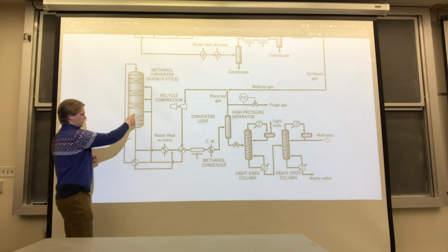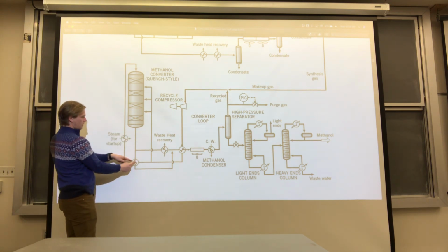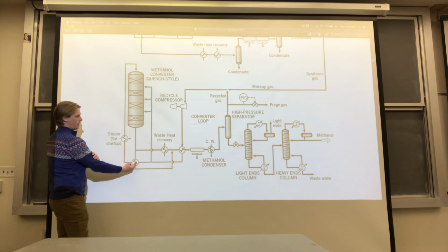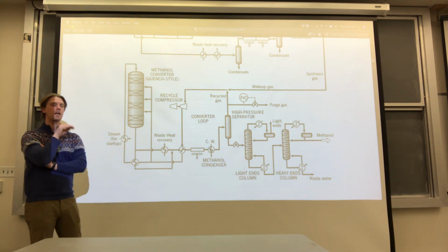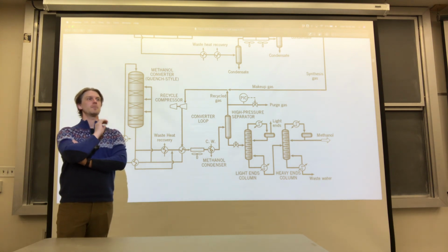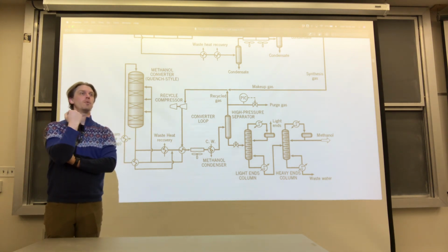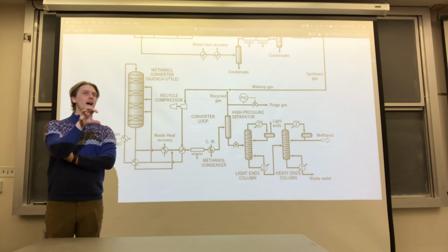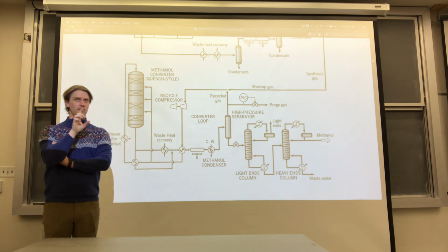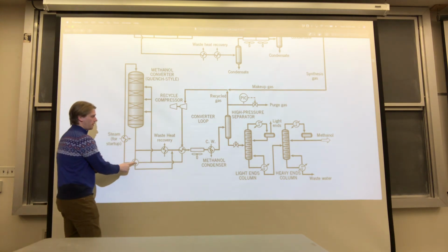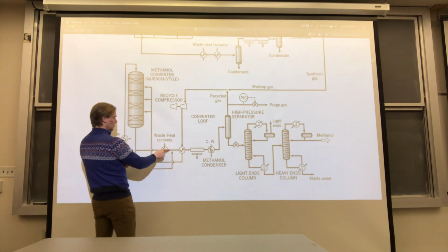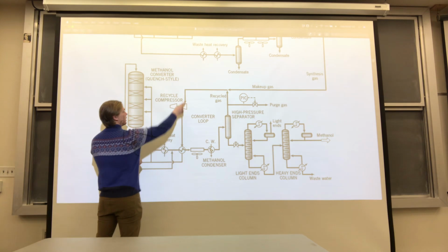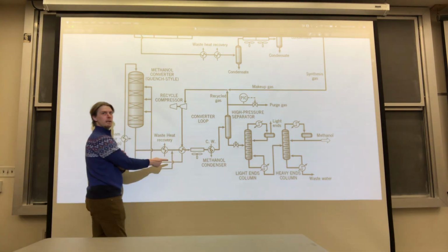Okay, so then that comes down. Some of that energy is taken away from the process to preheat the stream to get it to a high enough temperature that the catalyst becomes active. The reaction will happen readily, but it doesn't get so hot that it deactivates the catalyst. Okay? Then we will send it out down here through and preheat the stream again.